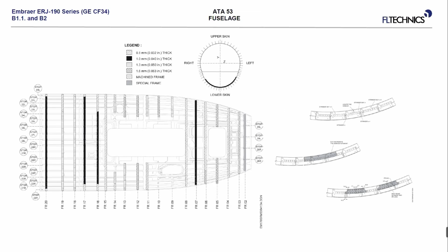That's why most of the times when we have this kind of damage on a stringer or frame, we have to contact Embraer. Their engineering team will make calculations and advise you on the proper repair. When the structure professionals have the instructions for the repair, it's not a problem. They just need the spare parts, the rivets or clips or whatever they need, and they can perform the repair and certify.